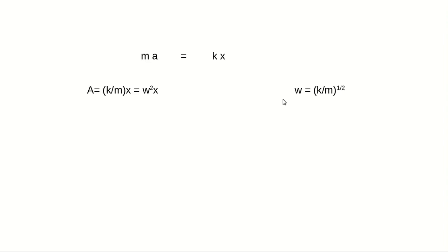So I want the dependence of frequency on the length of the cantilever. The force constant or the spring constant k here is dependent on the length of the cantilever or the vibrator. Similarly, we know mass is nothing but density into volume. For a material, density will be constant, but as I change the volume, mass will be changing.